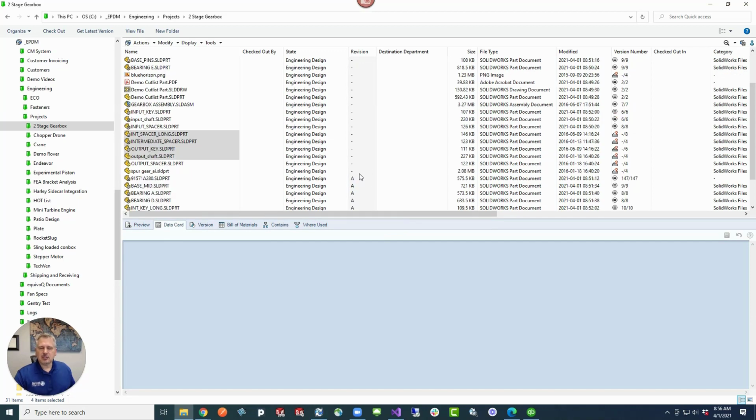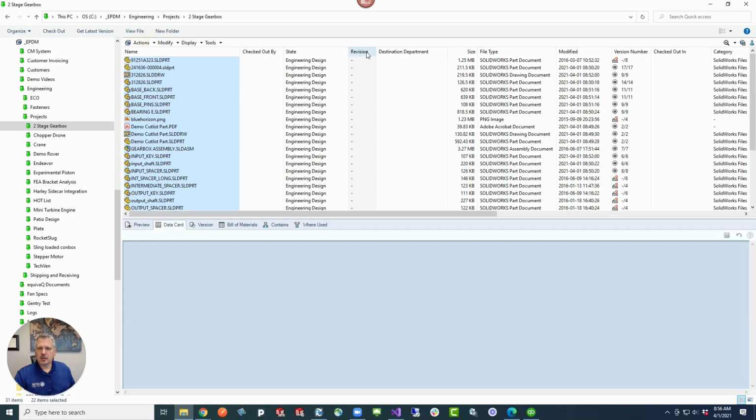So all these dashes, I'm actually going to bump them twice to go from dash to B. And then these A's, I'm going to bump them once to go to B. So let's go ahead and grab those. And again, if you've got metadata and you use details, then you can actually sort by metadata on your data card. There's a nice hint for your users.